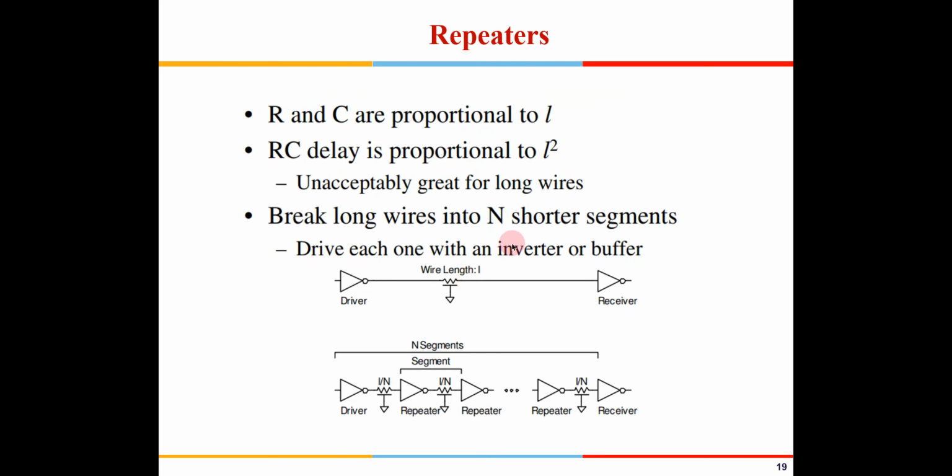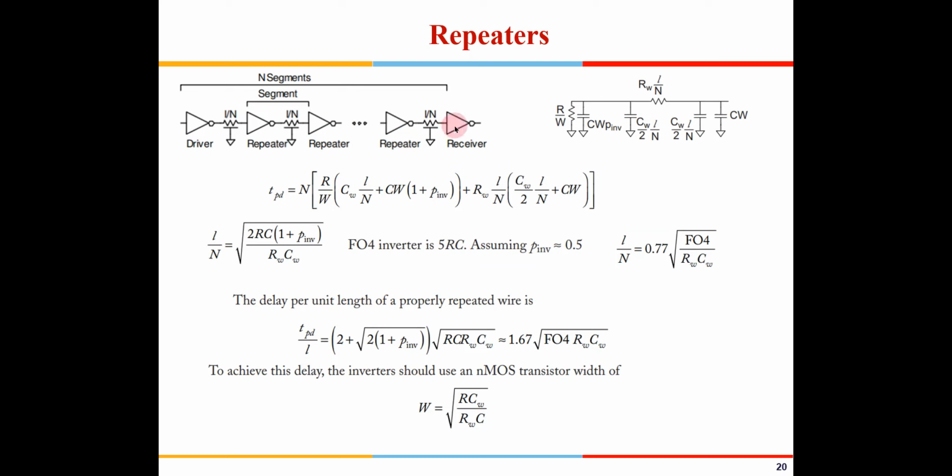And also, instead of having a long wire, if there is a requirement, we can have in-between repeaters. So you can divide it and place inverters in between. So that will speed up. Now if you see here, these inverters have been placed out here.